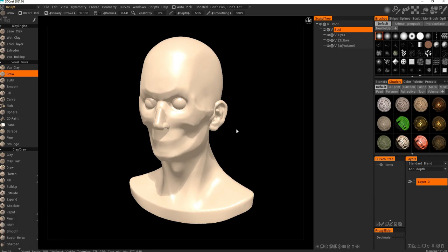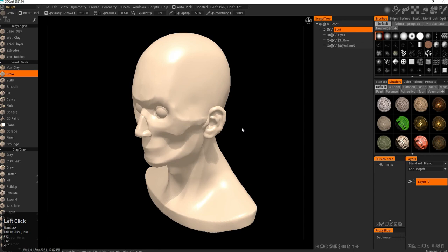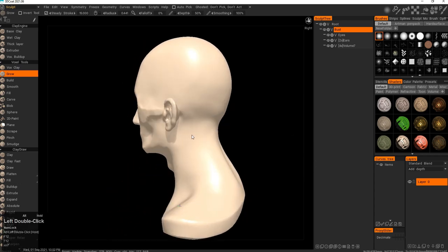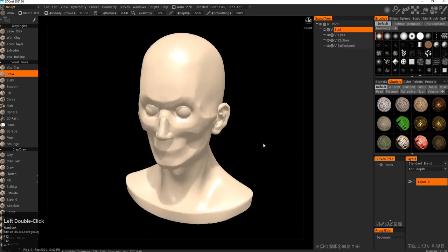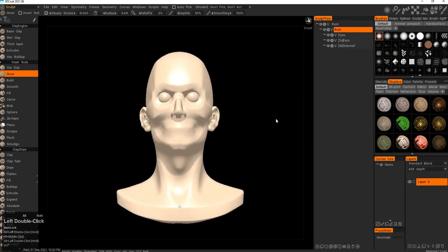But having real-time shadows on slows down the performance, quite a bit. It overrides the environment maps, the HDRI lighting, and it can slow down the scene maybe like 3 times, 4 times. I know people who comfortably work on a 100 million triangle mesh without the lighting, and once they turn it on, it becomes way slower. So be aware of that.